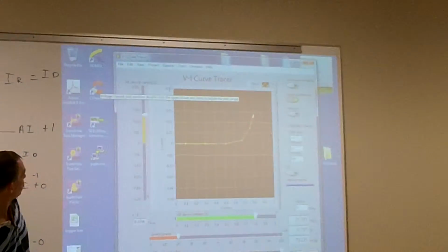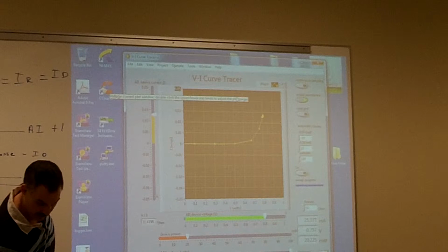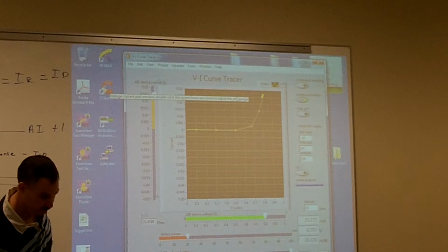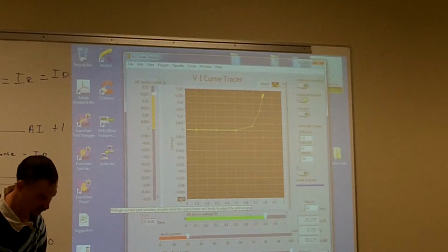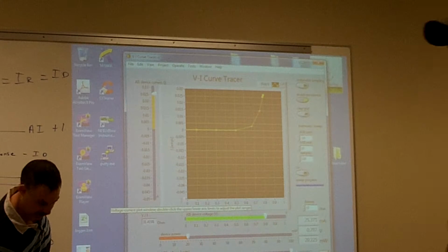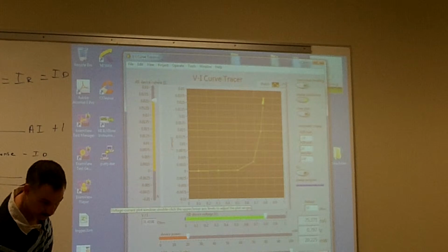More than 0.03 amps, we can change that one also. We know that we never go negative on our current, so you might want to leave it at a little bit of a negative so it kind of gets it up off the line. Just say 0.01.